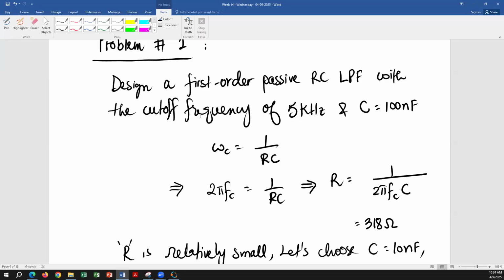I don't know if that is what you're asking or what exactly? You can do it graphically always, remember. Always graphically. But if you don't have the graph in front of you and you have to do it mathematically, no, hold on. You are taking the magnitude of the transfer function and you are trying to find out what is the value of omega at which the magnitude is going to become 0.707, right?